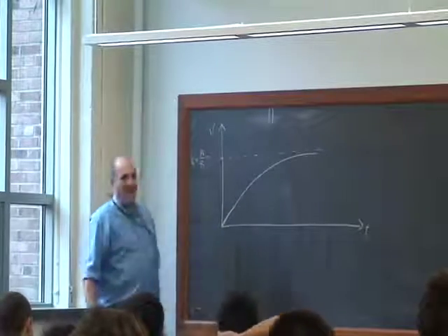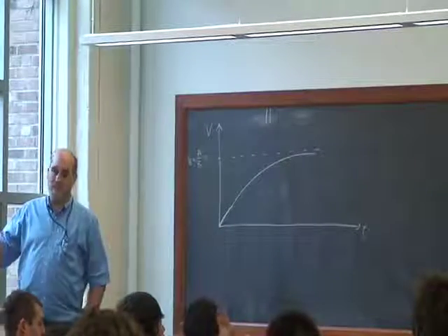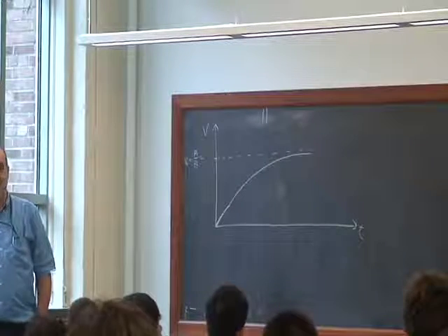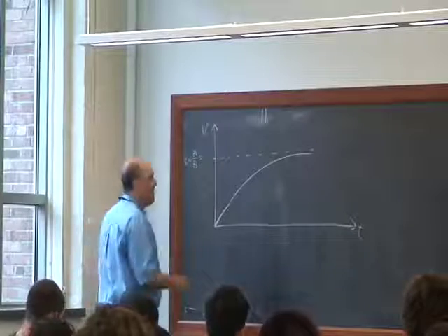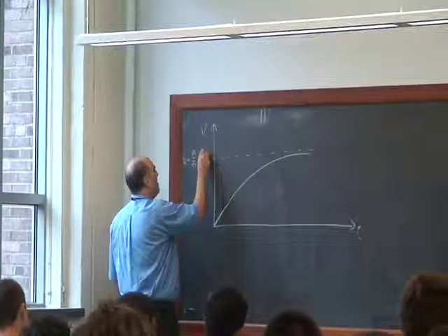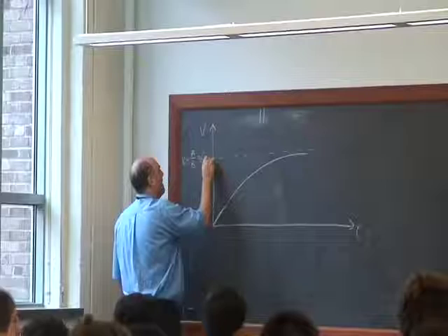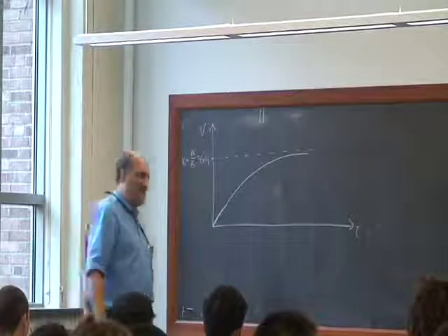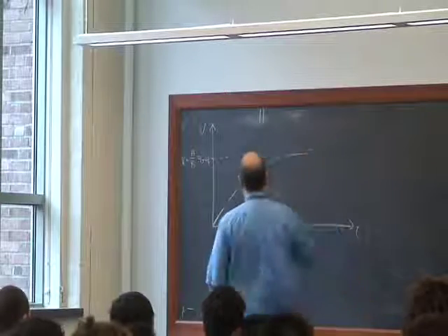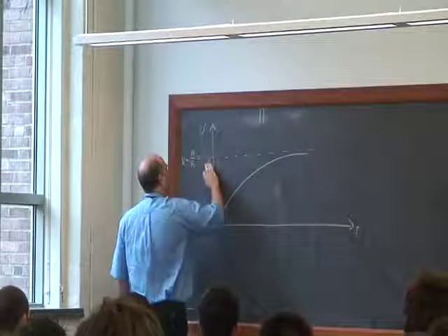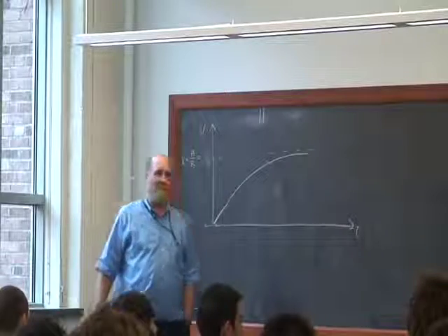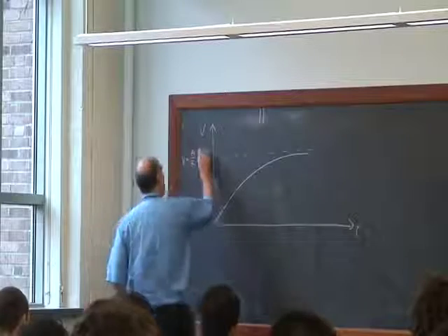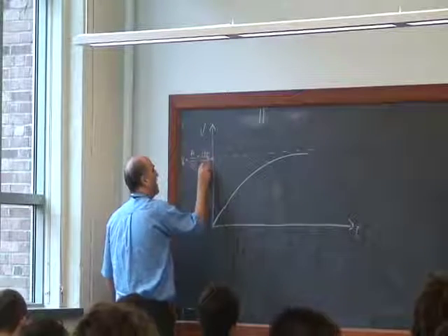But another way to think about it is, what is that asymptote? That's when you're pedaling so fast that you apply no force anymore. That's when you're pedaling at what we call omega F. And how fast is the bike going when you're going at omega F? Well, we just use the gear ratio for that, and that's G times omega F. We said the velocity of the bike is the gear ratio times omega F. Is that right, or do I have the reciprocal of that? Let's think about it. I said the gear reduction was G, so this was omega F divided by G.